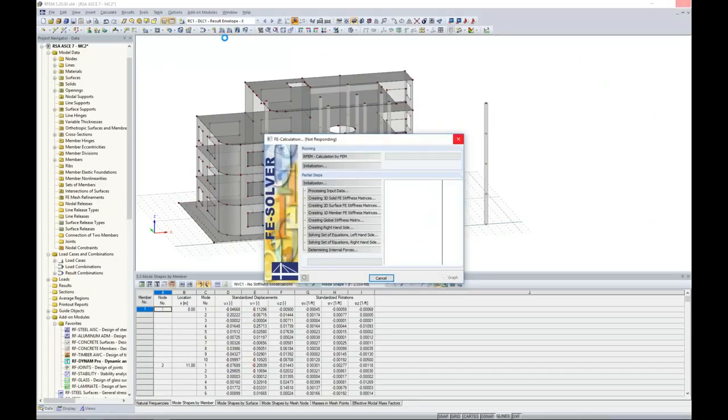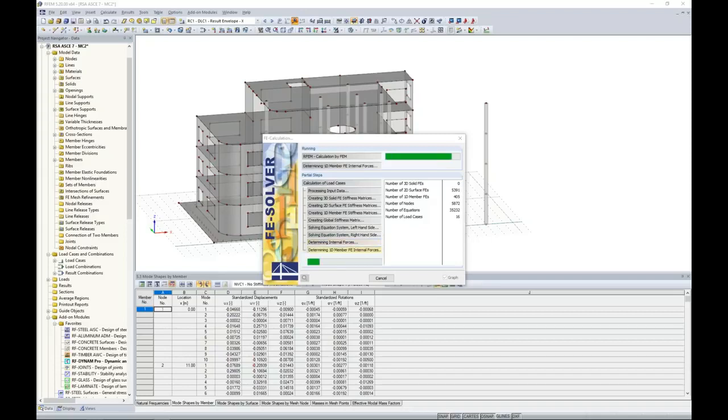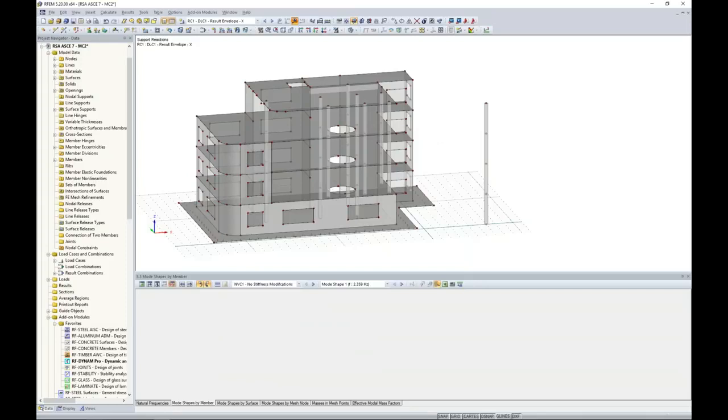The program's submeshing it in the background. Now remember, this column has absolutely nothing to do with the analysis, so it's not contributing any stiffness. Rather, we're just taking all of those mode shapes which are applied in the X direction and combining them per the CQC rule for this result combination. So eventually, the program will present to us our results here.